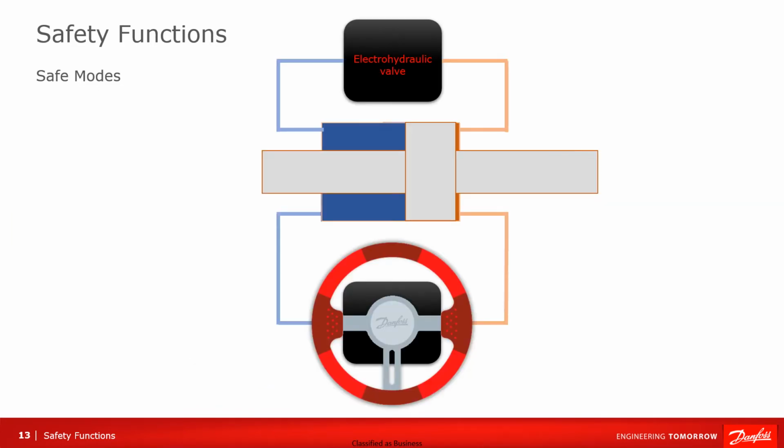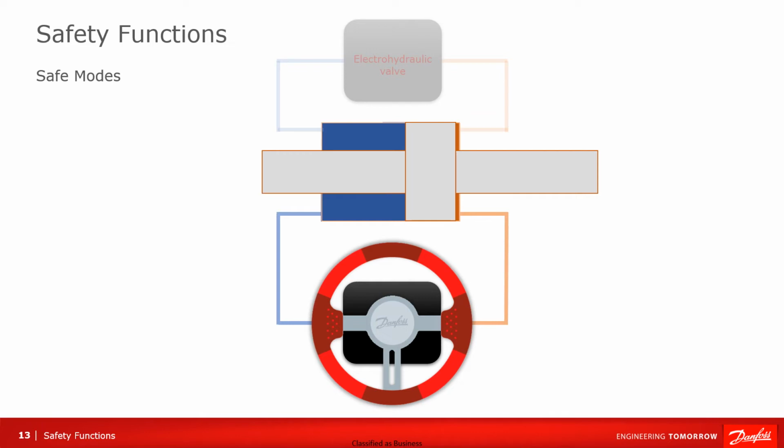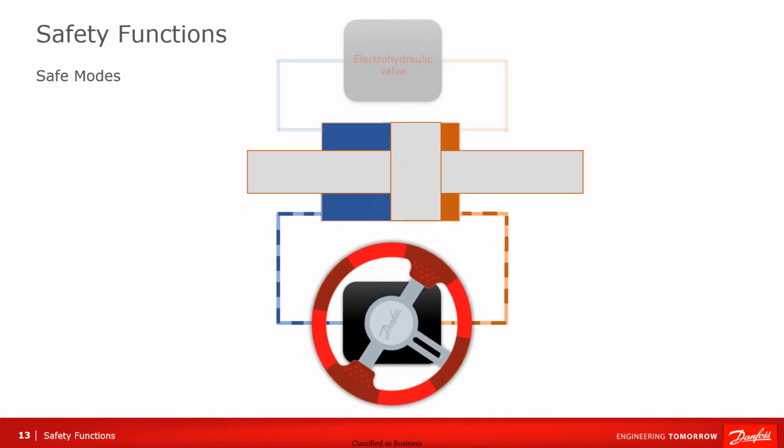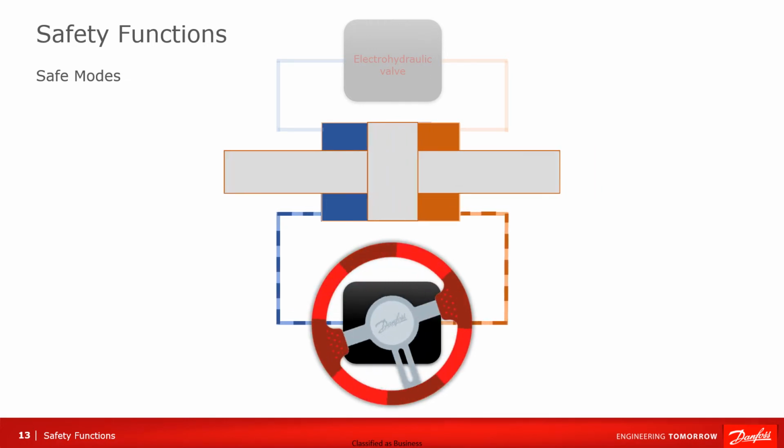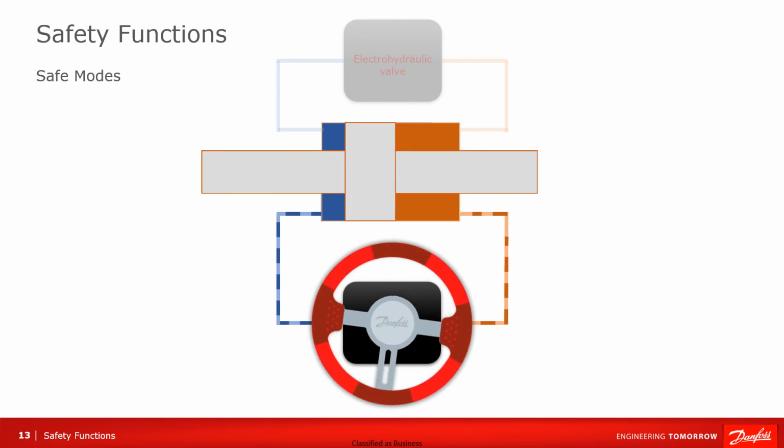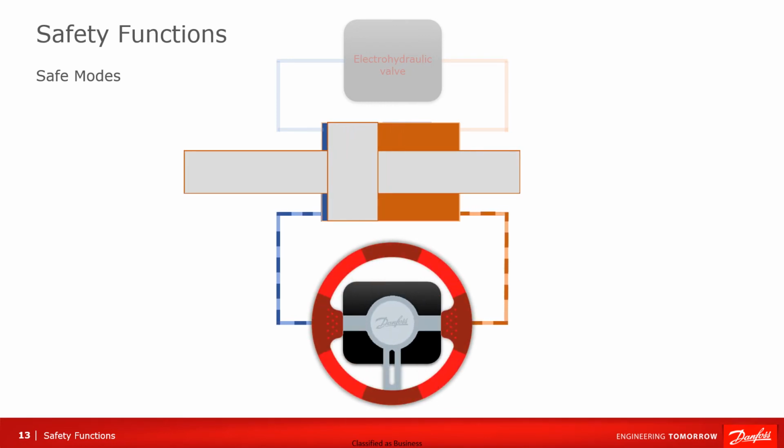An important feature of the PVED CLS is to be able to safely use and/or shut down the electro-hydraulic steering. These functions are used to safely control the EH steering capabilities of a machine. For example, Safe On-Road mode limits the steering to just the orbital steering.